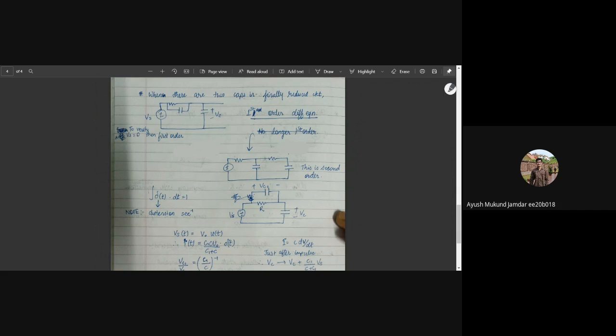Let's say the voltage source is a step function, that is, it steps to a certain constant value at t equals 0 and is 0 before t equals 0. So both the capacitors, the voltage that they might have for t less than 0, is always controlled and restricted by the KVL. So indeed, we don't have two independent state variables, two independent voltages of the capacitor. So it is a first order differential equation.